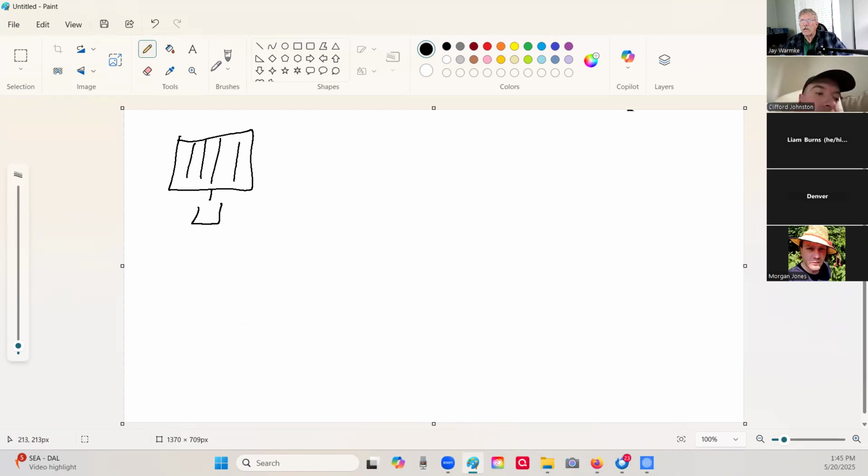Let's say this is your combiner box or junction box. And the only difference between a combiner box and a junction box is if you have multiple strings entering in and then you only have one pair of wires leaving, that's going to be a combiner box. You're making a parallel connection in the combiner box. A junction box just passes the wire through.